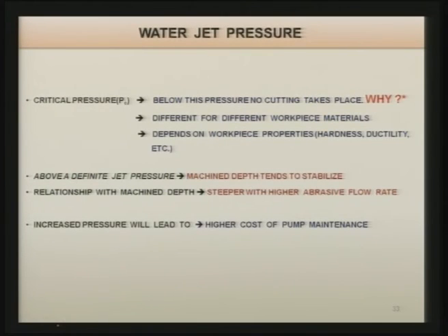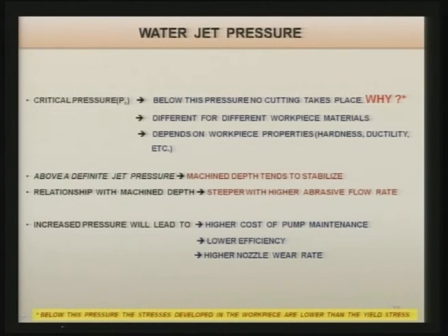Increased pressure will lead to higher cost of pump maintenance, because if the pressure is very high, then the maintenance of the pump becomes more expensive because of more wear and tear. It gives lower efficiency at very high pressure. Higher nozzle wear rate is also observed with very high pressure. Below the critical pressure, the stresses developed in the workpiece are lower than the yield stress. That is why you do not get any removal of the material.